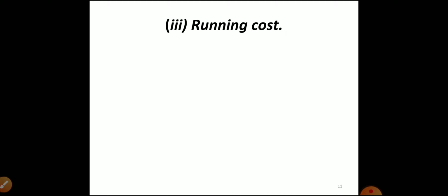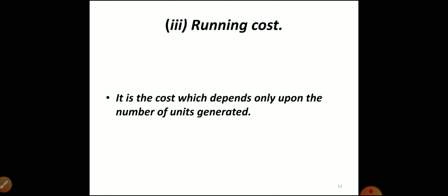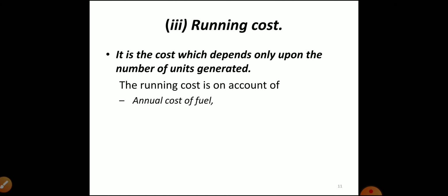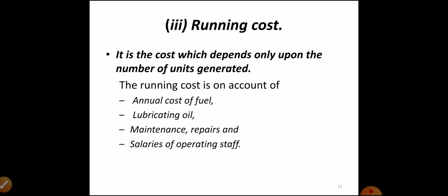Now we will see the running cost. What is the running cost? As you know, the running cost depends upon how many units have been generated. The running cost is on account of annual cost of fuel, lubricating oil cost, maintenance, repairs, and the salaries of operating staff.